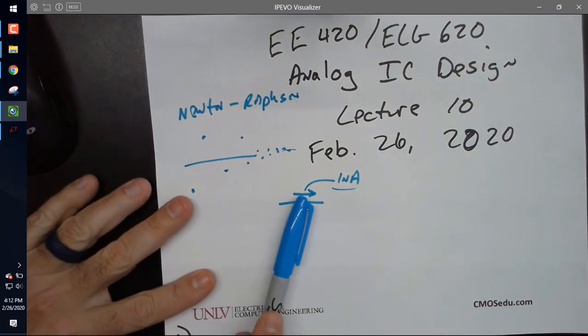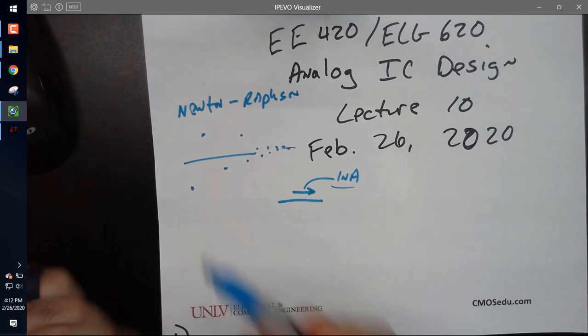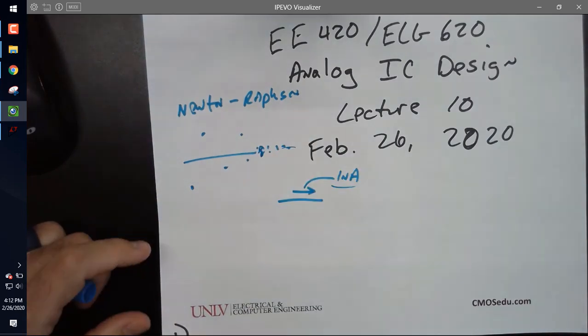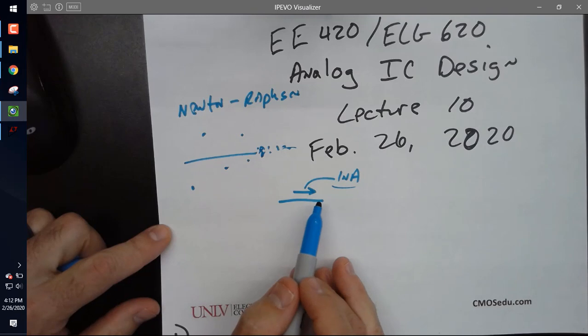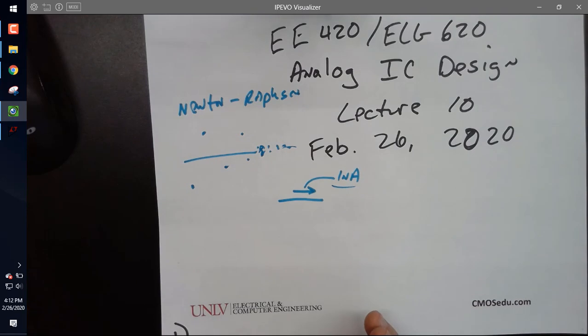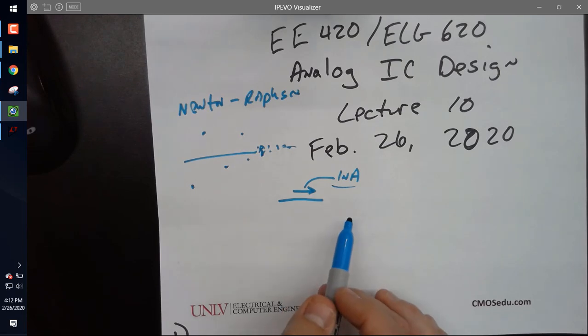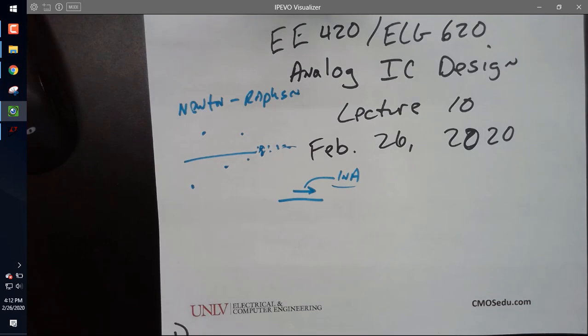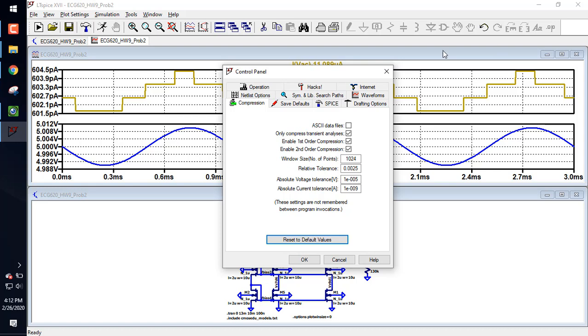So it says, whenever this variation becomes within 1 nanoamp, I'm going to stop simulating. But what if you have a 10 amp current? Well, it's kind of ridiculous to stop simulating when you get within 1 nanoamp, because that's tiny compared to 10 amps, right? So there's this other term in here that says relative tolerance, 0.25% or 0.0025.